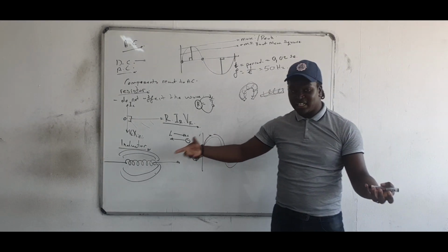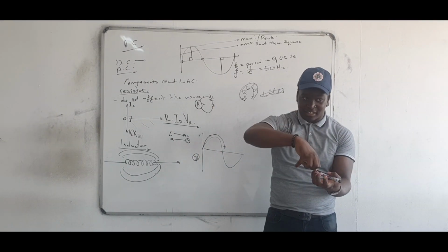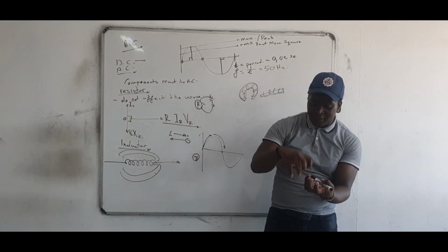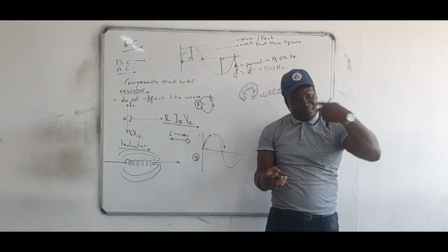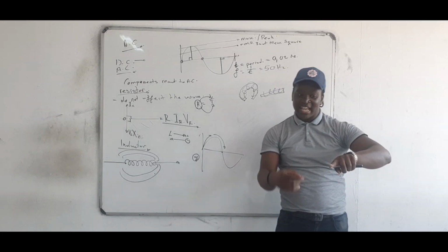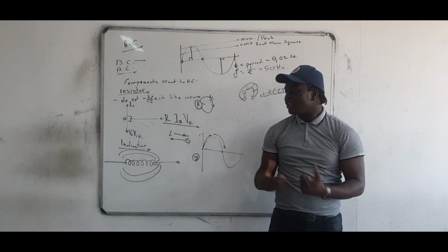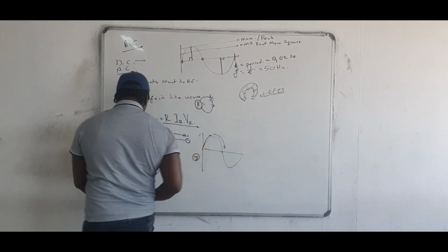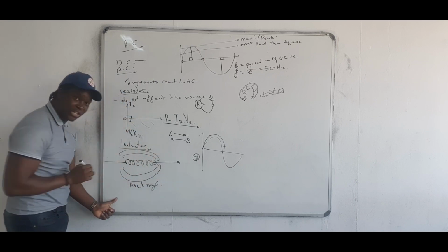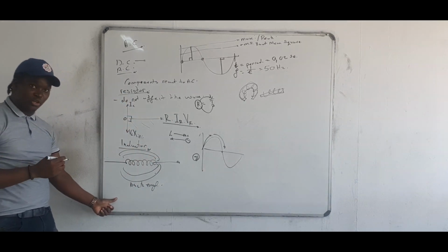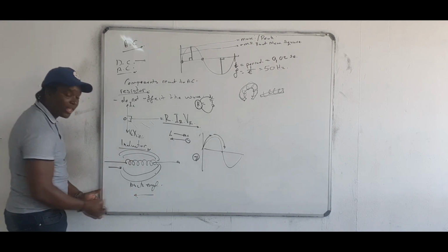That means the magnetic flux is also going to collapse onto the conductor, and when it does, an EMF is induced into it. That induced EMF then opposes the original one. Actually, it is called back EMF, because it always opposes the original one. So if the original EMF is going in this direction, the back EMF goes in the opposite direction.